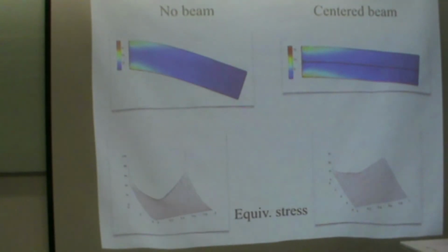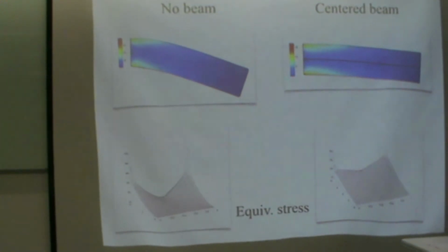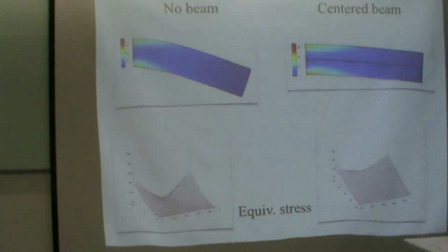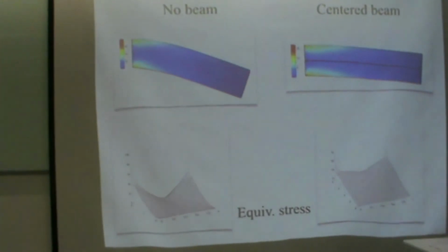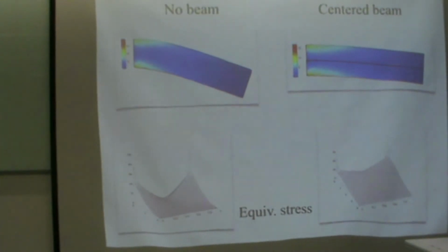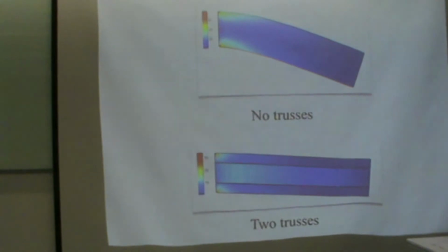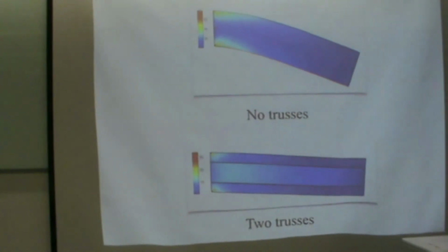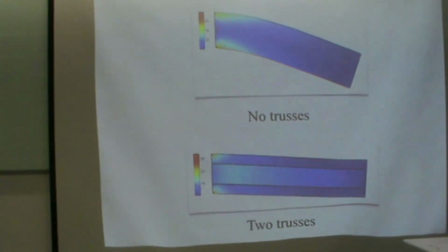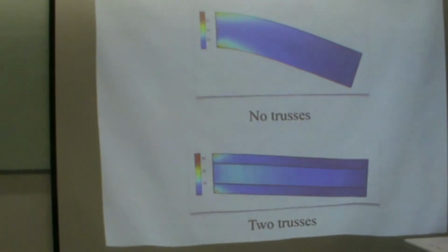So now we can simply try to put in a beam in the center here. If this was just a membrane, it wouldn't have a stiffening effect because it's in the middle. But now when I put this beam in the middle, it actually stiffens. Or I could have trusses giving this similar effect, because if I have trusses sitting here, it will have stiffening.